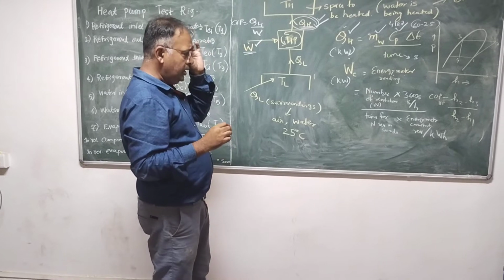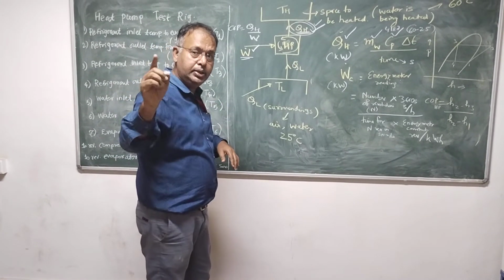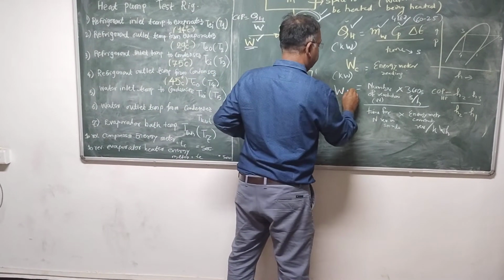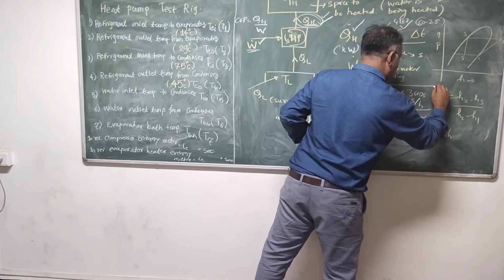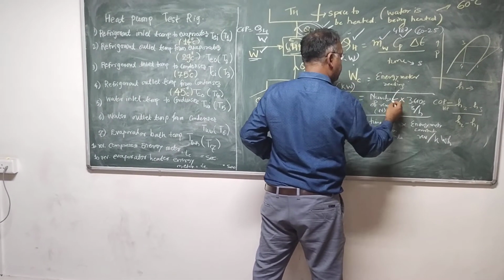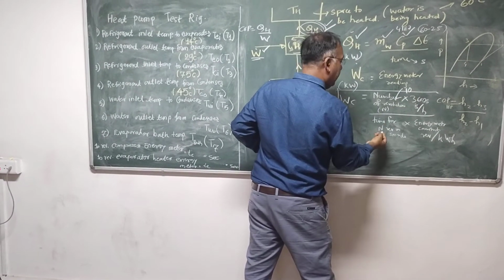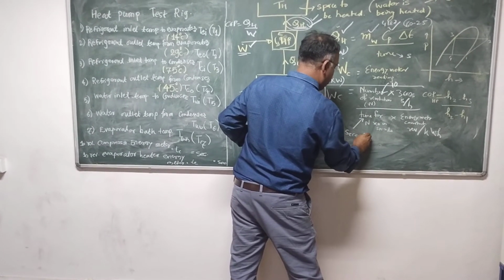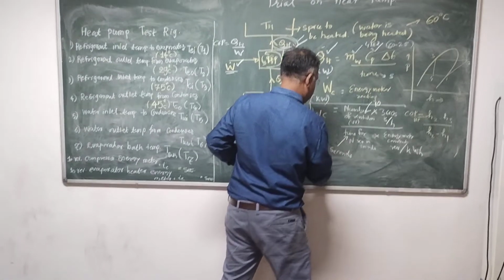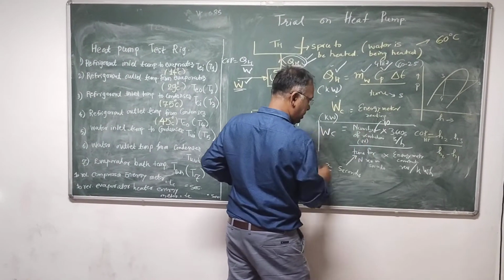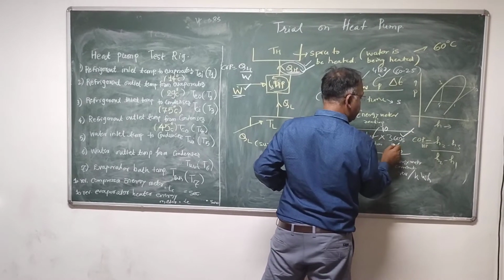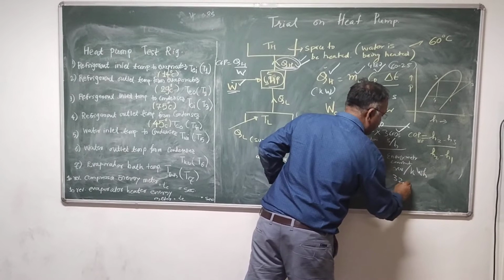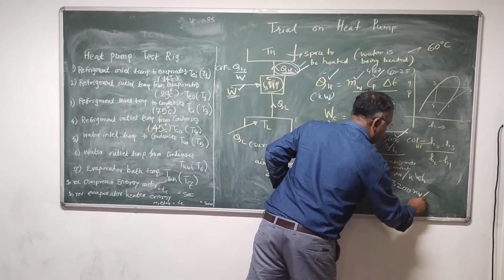And for finding the power consumed, as I had explained, either you take the kWh1 and kWh2 upon time, or you use this formula. If I had noted down the time for 10 revolutions, then n becomes 10. The time you can note down in seconds, whatever time, so 8 seconds for 10 revolutions, into 3600 to convert the seconds to hours, and the energy meter constant, in this case, is 3200 revolutions per kWh.